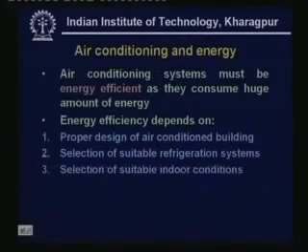And the third factor is the selection of suitable indoor conditions. As I have shown, the optimum indoor temperature varies anywhere between 20 to 26 or 27 degrees centigrade. And you will see later that if you are trying to maintain a lower temperature inside the conditioned space, that will lead to higher energy consumption. That means a lower conditioned space temperature means, in general, higher energy consumption. So if it is not absolutely required, we must try to keep the temperature on the higher side to reduce the energy consumption. And several factors again come into picture here.